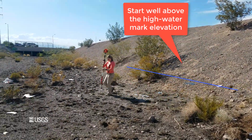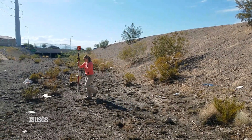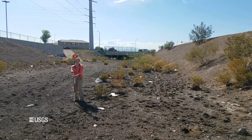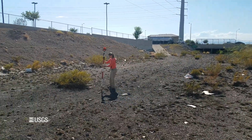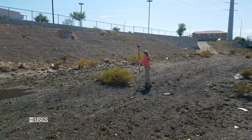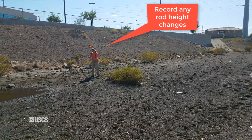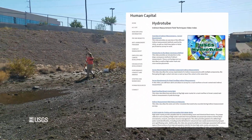Start and end each cross-section at points well above the high watermark elevation. You don't want to have to extrapolate your cross-section geometry later in the office. Make sure you define the major changes in the shape of the channel as your rod person moves across the cross-section, ideally left and right edge of water for each cross-section, and document any characteristics of interest. Remember to record any rod height changes. You can find more information on surveying both high watermarks and cross-sections in the High Watermarks and Cross-Sections video in this series.